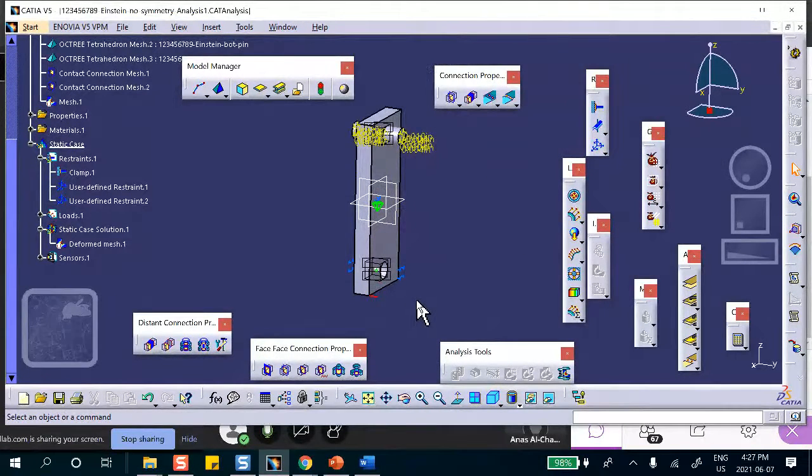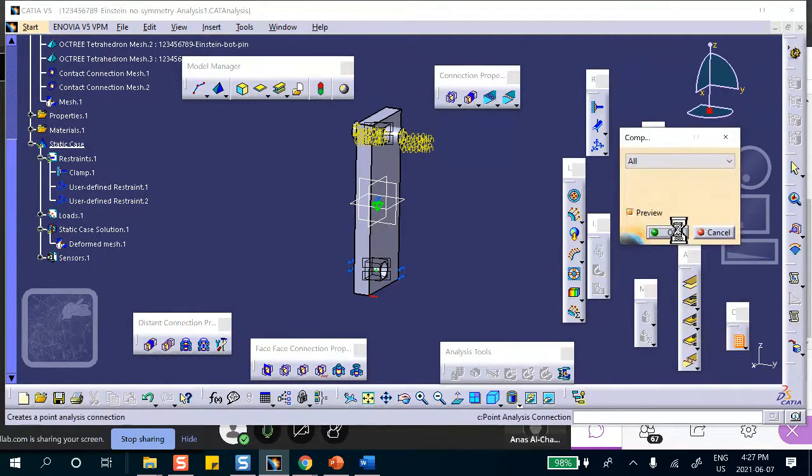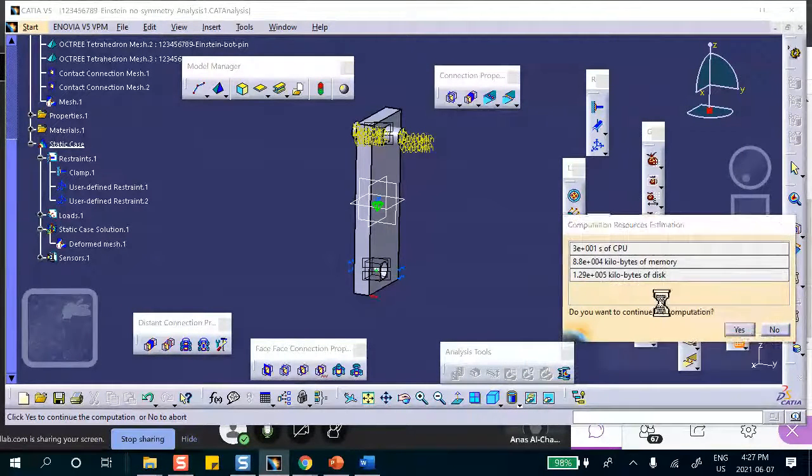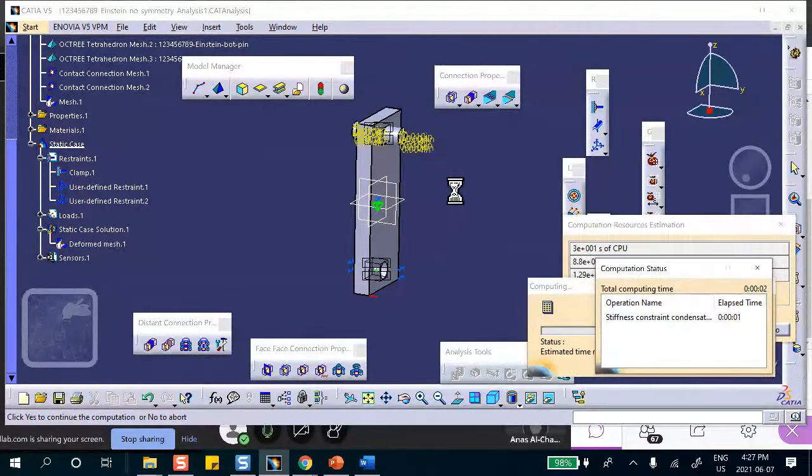I mean, let me put it this way. If you took the edge and did that, you're going to lose marks. If you took the face and did that, you're going to lose marks. Because when you fix the face or edge, you're doing something else. This is preventing rigid body motion. It's just one point that you need. One point. And you're learning it. This is not the first time you've done things like this. This time it will run.